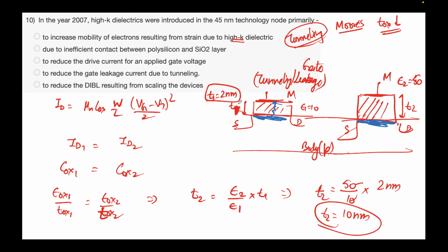There are other things, yes, for instance the oxide trap charges, the insulator trap charges, and so on. Those things are there, but on a first level, the problem seems to have been solved, right? These are just numbers that I generated, but the reason for this was to reduce the gate leakage current due to tunneling. Tunneling becomes prominent at less than 10 nanometers or even lower, at such low distances.